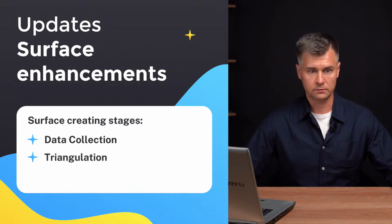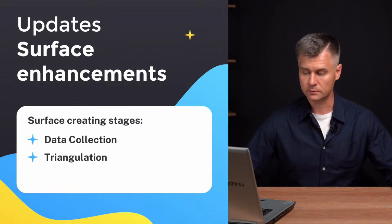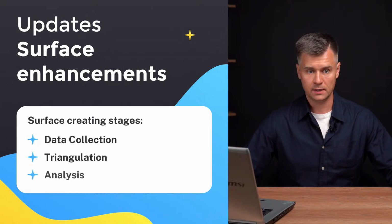And next, triangulation, connecting the data points to form a network of triangles. This process can be done using various algorithms such as Delaunay triangulation. And the third step is the surface analysis, performing analysis such as elevation, slope, contour generation, etc.